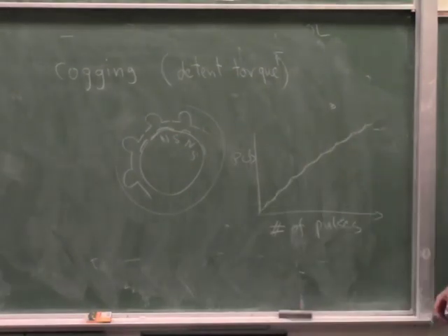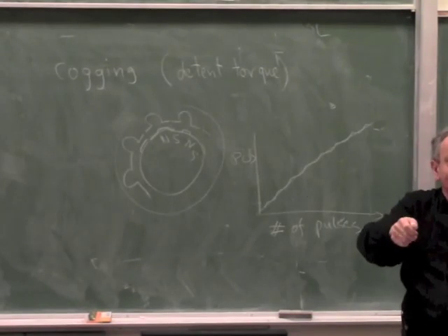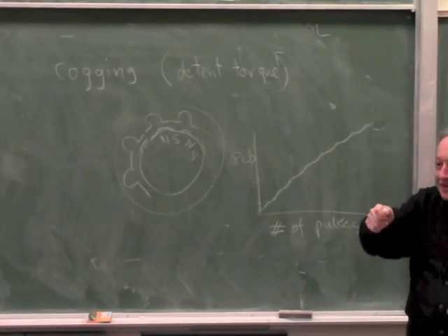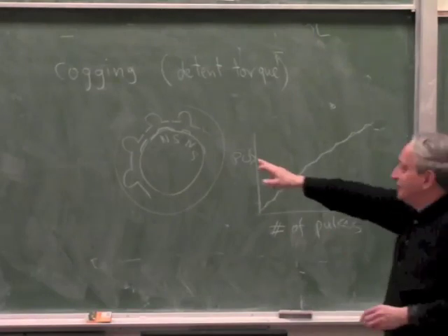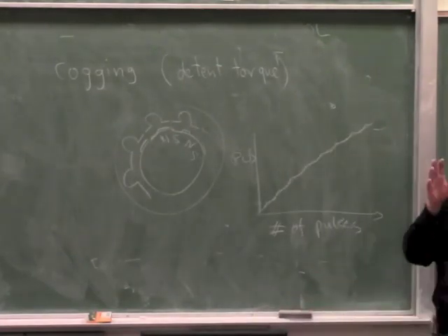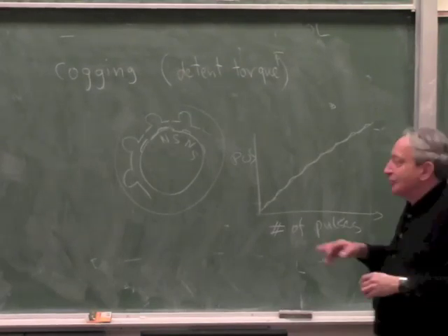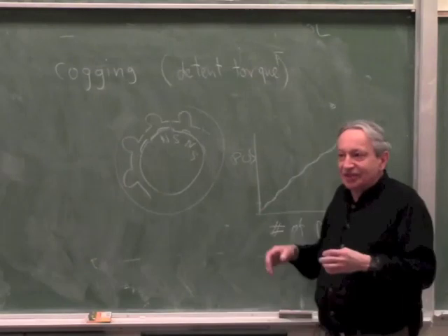Okay? The same thing you feel when you take a stepper motor and you turn it without power. You feel it does tick, tick, tick, tick. It doesn't go smoothly because you feel those natural positions. Okay? So again, if it was perfectly laid out inside, the flux was perfectly distributed, under power it wouldn't have that. But there's always a signature.